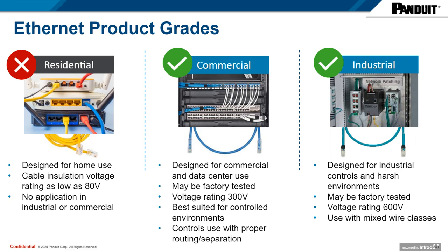Each of these locations use specific cabling types based on the required application. You may not be aware of it, but you need to specify and use different grades of cable to fit the application, just as you would any other electrical wiring. And what this really comes down to is the jacketing and the cable construction of these different grades of cable, right? And learning to discriminate between those.